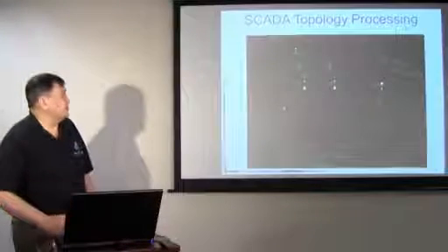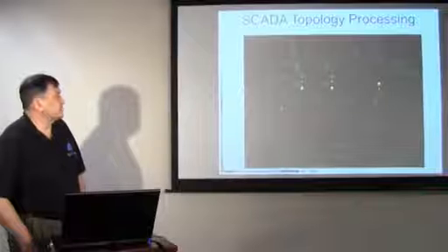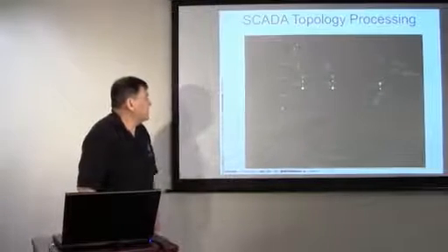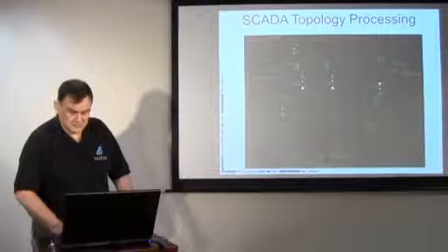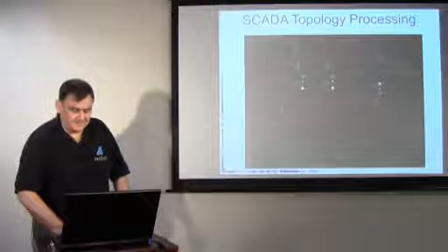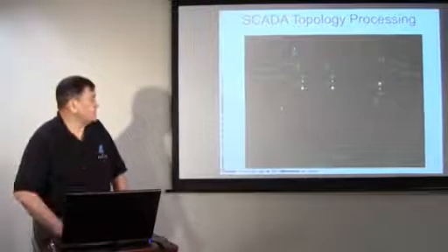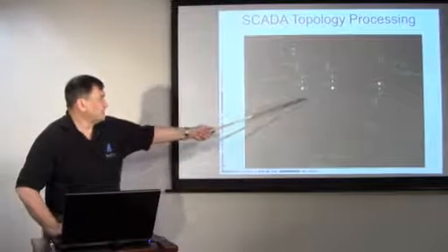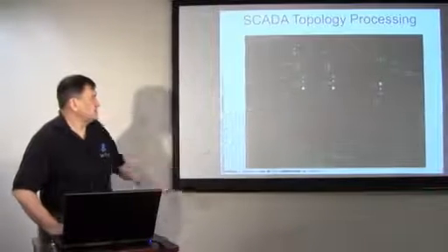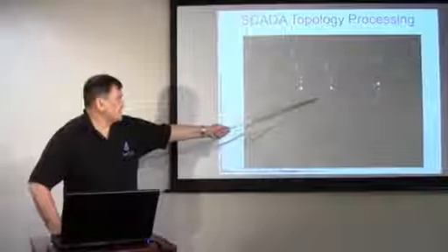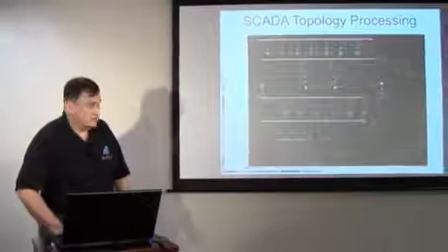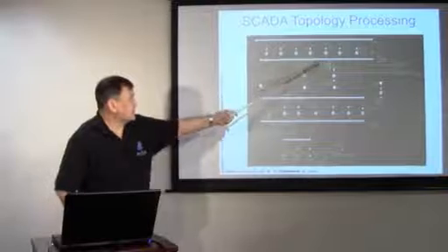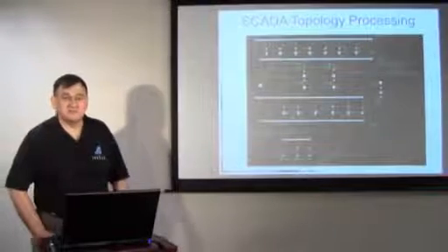We can show the importance of switching by going down to this case. It's a 34.5 kV network. A very severe type of fault is to have a bus fault with a stuck breaker. So we've got a fault on this bus here. Because the breaker is stuck, literally we clear out the entire substation.